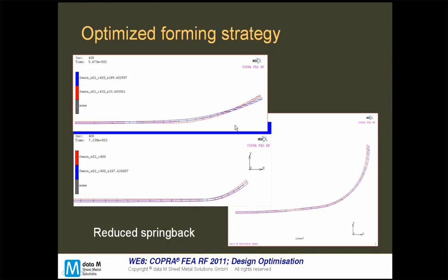In this case, we changed the calibration method, changing the way we work. Working with the smaller inside radius reduced the spring back because the lower ratio of inside radius to thickness and material properties makes the spring back behavior get minimized.